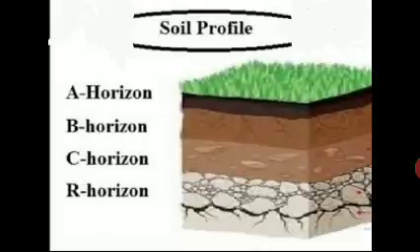Granular: fine-grained soils have granular structure in which water entry is rapid, with better seed germination, and as such they are desirable for irrigation as large voids provide space for circulation of air. Prismatic: in prismatic structure, the movement of water is mainly vertical and as a result, the water supplied to the root is poor.